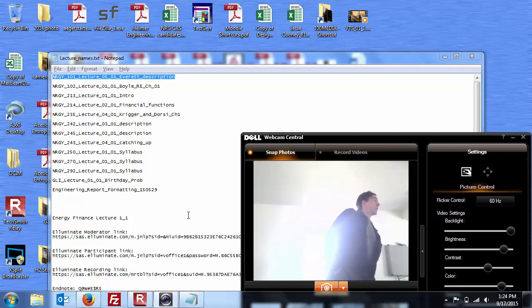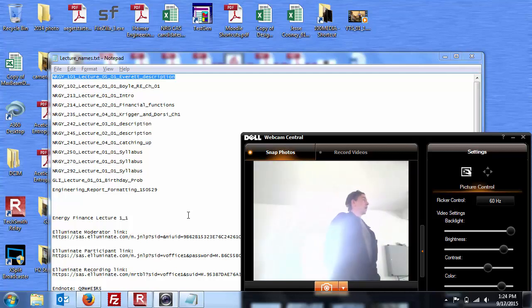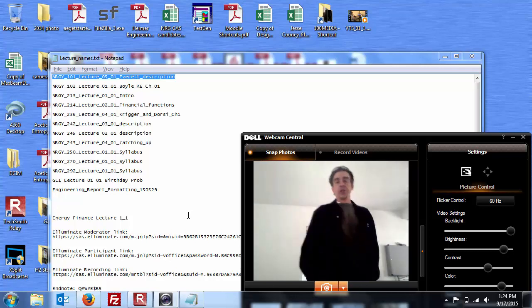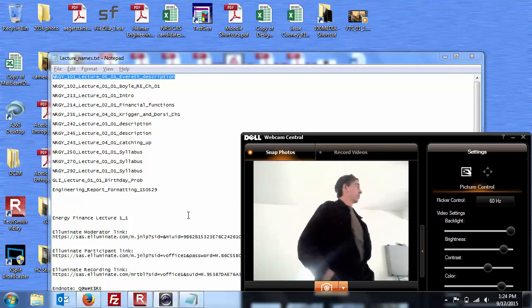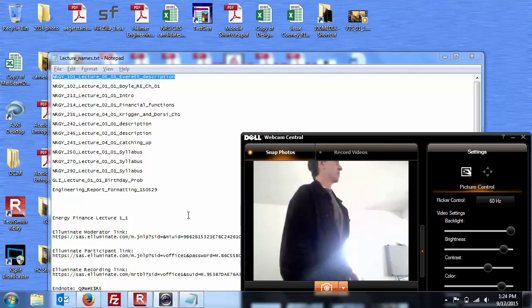It says if you use 5 60-watt light bulbs for 8 hours per day, how much energy is wasted per year, or how much energy is turned into heat per year? The next part of the question: if electricity costs 10 cents per kilowatt hour, how much does this wasted energy cost each year, or how much are you paying to heat your house, whether it needs it or not?